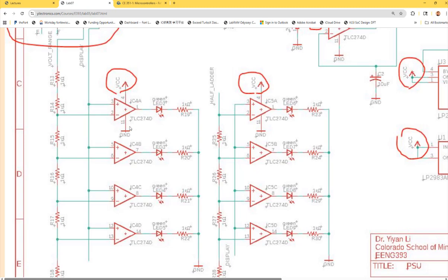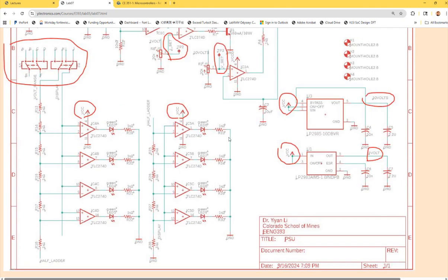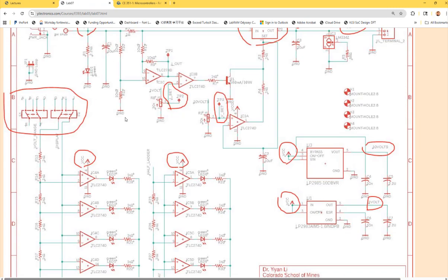Okay, keep in mind, if they're not in the same chip, you need to power them up and ground them separately. Any question on this? And I believe you all know that if you right click and name a trace with one name and you name another trace somewhere else with the same name, they will be electrically shorted, right? You all know that, right? You don't really have to draw a physical line to connect them, because the same name will keep them shorted physically. Okay?